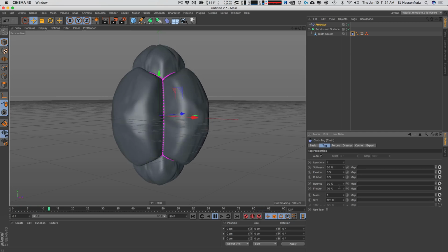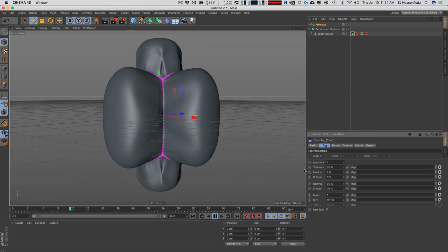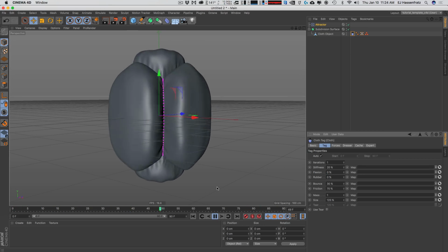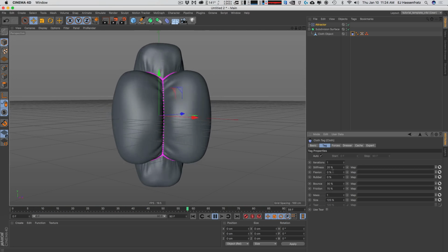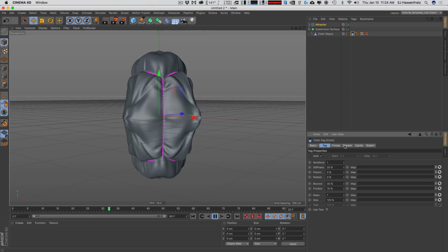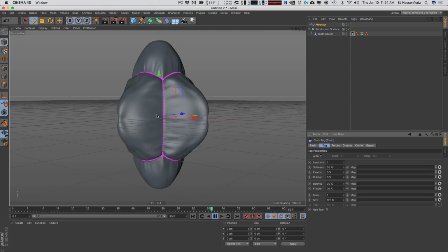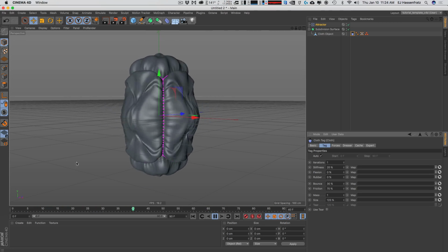And what I've found is that flexion doesn't really look nice for the kind of cloth billowing that I like. So I'm just going to turn that off altogether, okay? So no flexion, and you can see with a low stiffness value how this billows out and pulses like that. Now, since we're on the subject of this cloth pulsing, if you want to dampen the springiness and the undulation